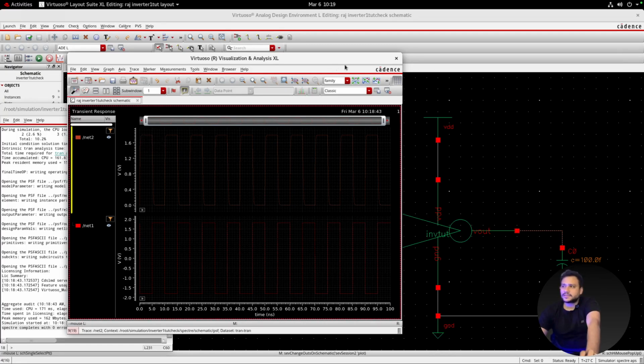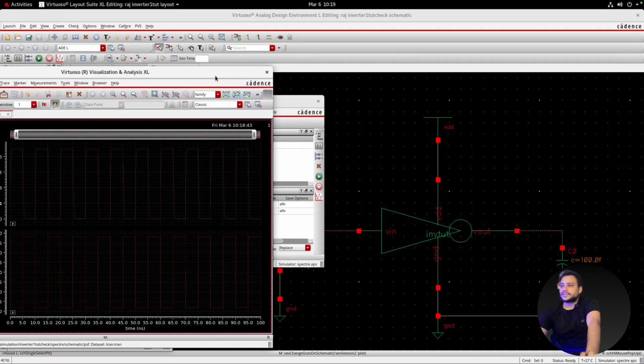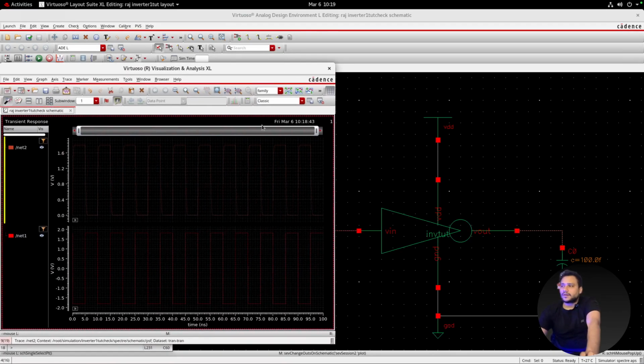It has some losses, because while charging the current from VDD, the PMOS will have some amount of power consumption. Power loss will be there. So from there the voltage drops, we are getting a lesser value. And here the complete value is 0 as a negative, because it's completely discharging when your NMOS is turned on. By this logic, I already explained how it works. So this is just a simple simulation to show you all.